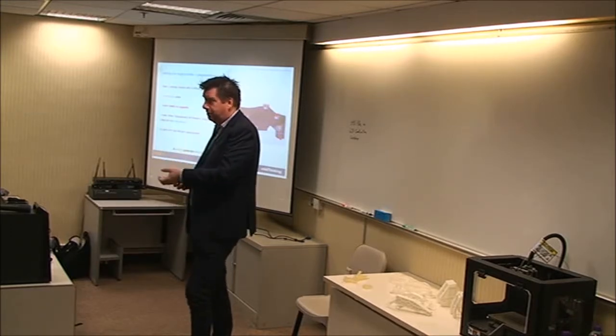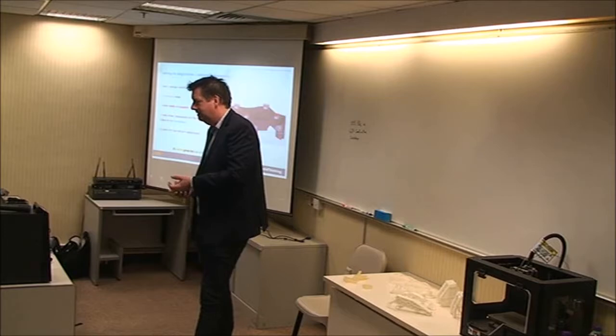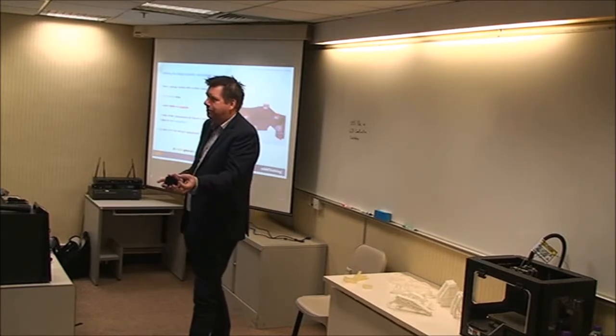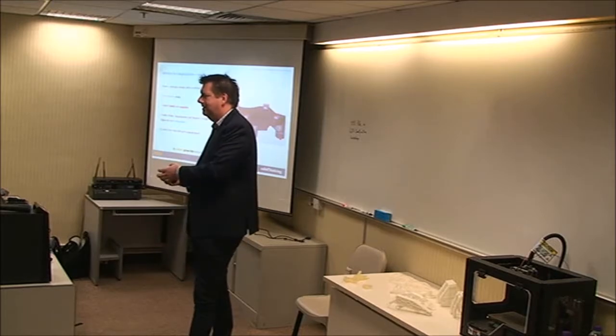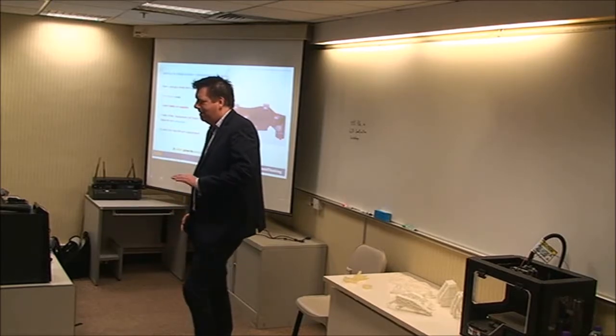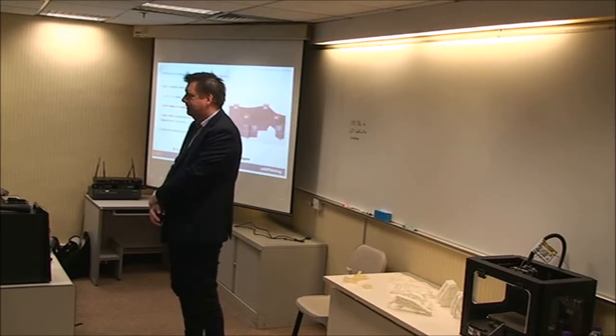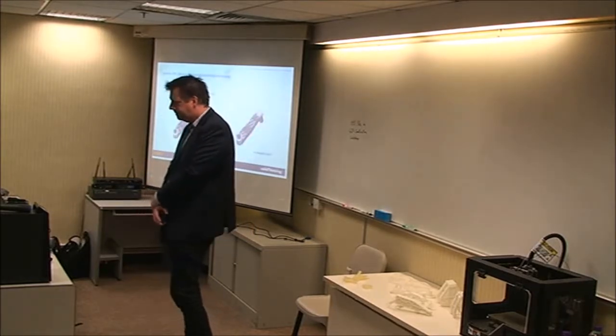What the topology optimization does, what Inspire does, is give you the most efficient material layout. It says how to connect my load points to my support points in the most efficient way. So that, in one slide, is what Inspire does. It takes a little bit more effort to make it work, but not much.